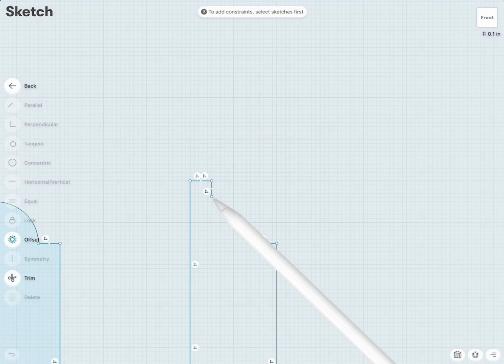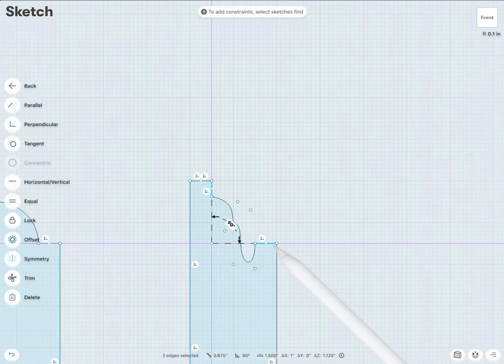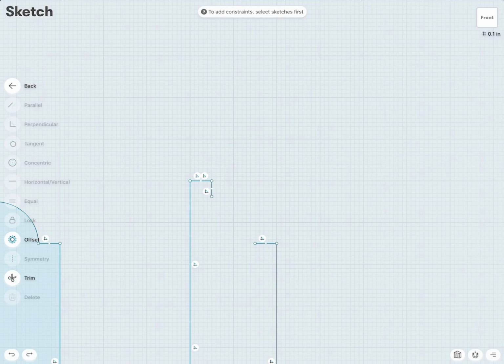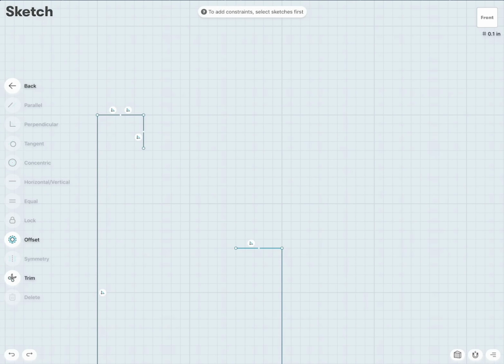So to use the spline tool, we start drawing a line and then press the button. Sorry, I said button, I meant obviously the pencil. And I'm just making a random shape here. And you see you can create nice curves. So I would like to have a nice transition from this line and then flowing into this line, so they're tangent. So for those who are not familiar with that tool, I can click, I need this one point there, then I could maybe go to there, I go to there, and I go to the end and release.